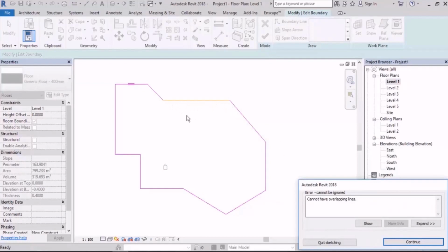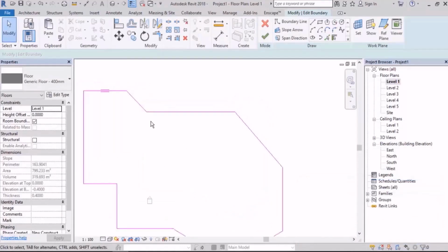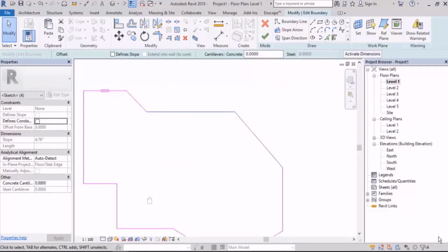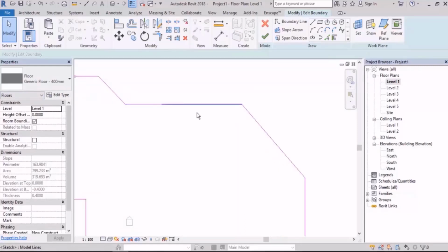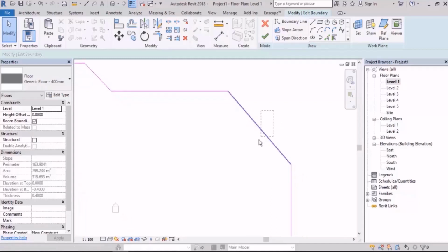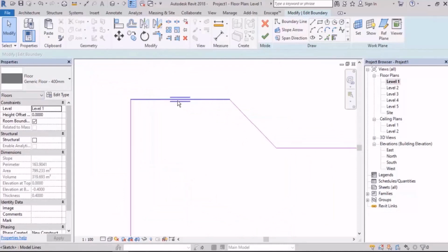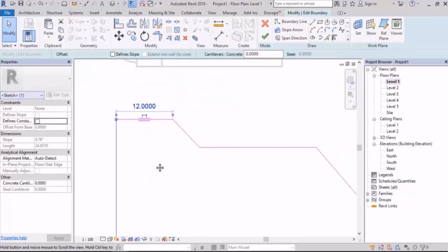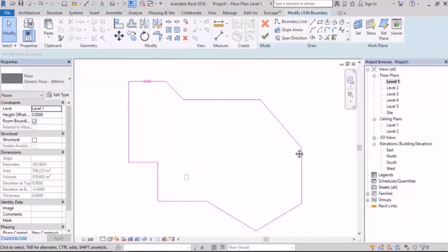Alright, now I want to tell you the solutions. I'll teach you two ways to fix this. Here, how many lines should we have? Two. But when I open a box here, I see, as you can see, that it says 4. We should have 2 lines here, but it says 4. Then you move your mouse on these lines, you see this is the 1, 2, and the 3, but where's the 4th one? Now you understand that 2 lines are completely on each other. So you draw a smaller box, and then you find out that these are 2 lines, one extra. This is one way, by opening a box. Now here it shows 2. And when I open a box here, it says it has 2 lines. This is one way that I use a lot myself.